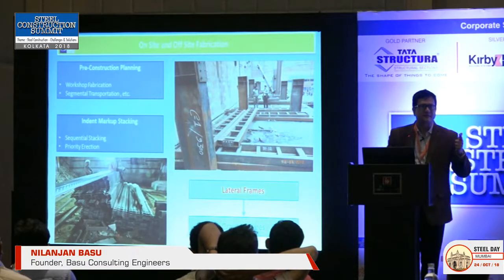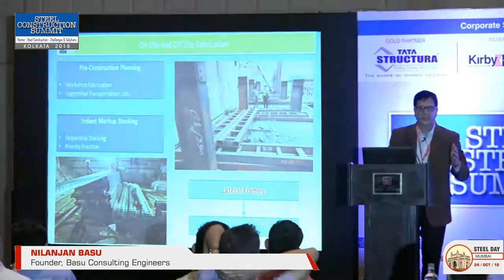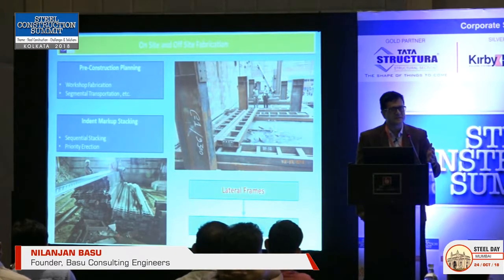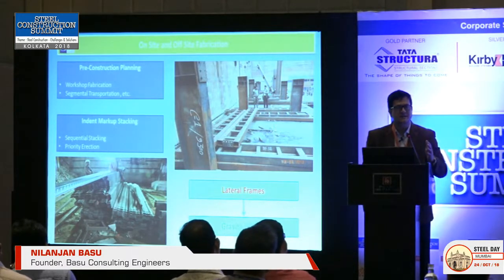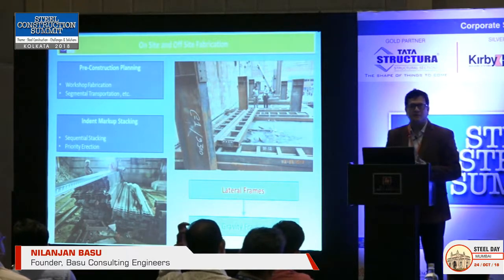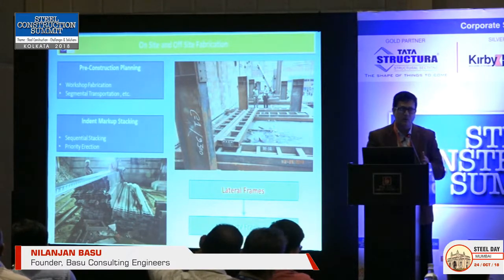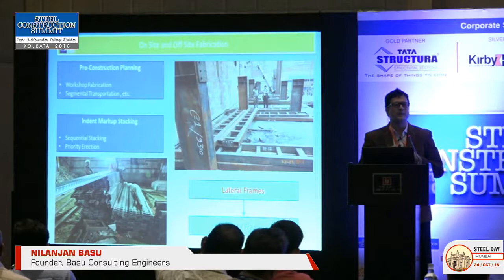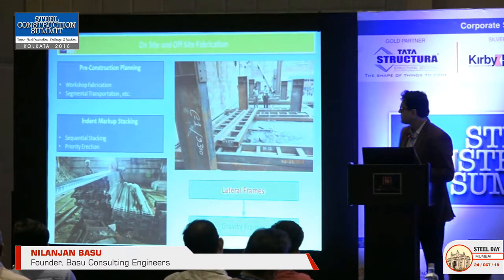Which girder, which framing is to be erected first, which material is to be supplied first. We ask the contractor for his limitations, how much he can transport. We base the design of the connection on his limitations or his transportation length. And based on that, we give him the drawings. We develop the drawings based on discussion with him, and not only based on where we can find the connection. We stop the wastage of that.